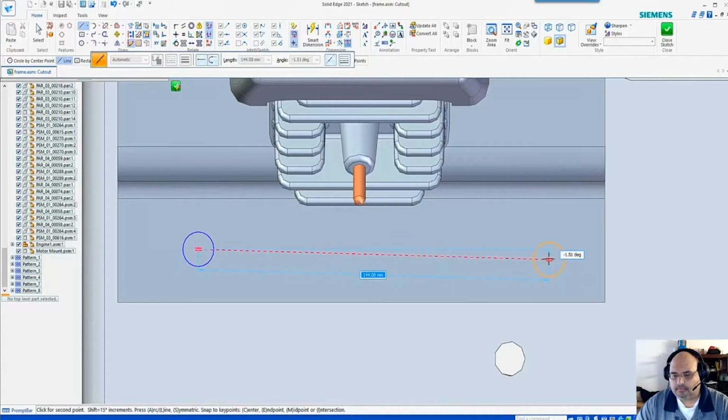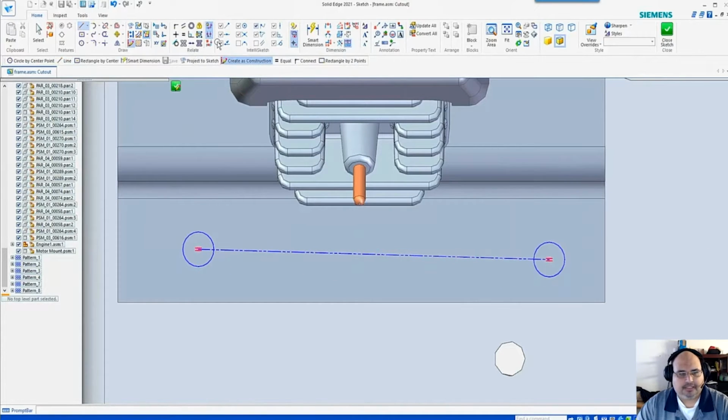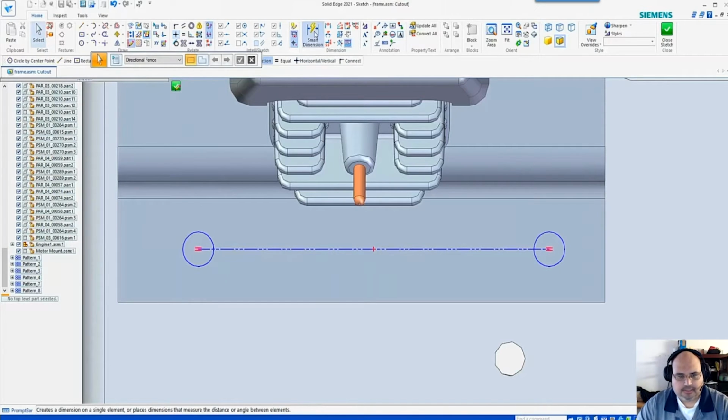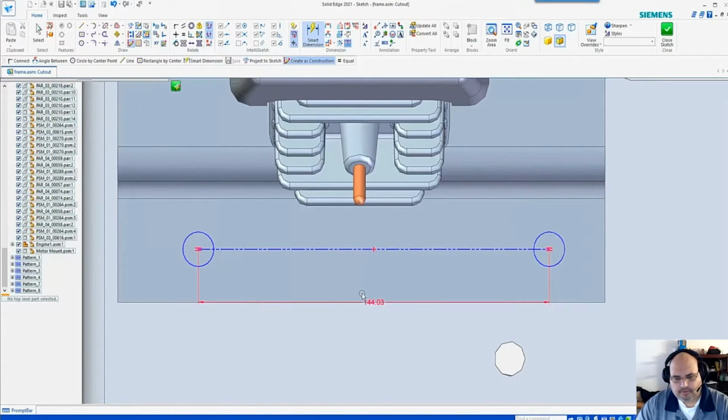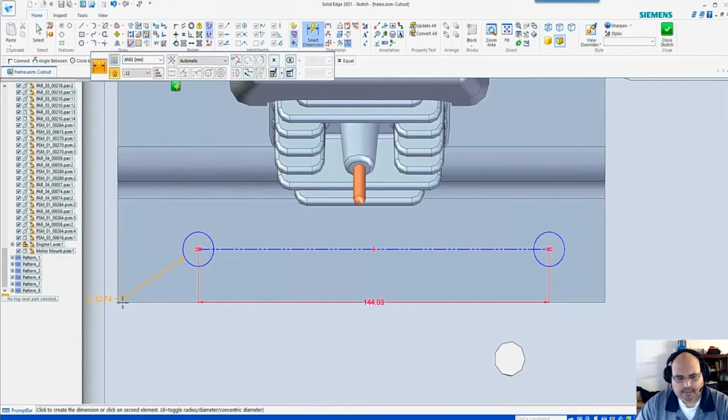Thank you. Okay, so going on from there, I connect the two, and then of course throw my horizontal vertical in there and make them aligned with each other, and then grab a center point and start dimensioning out, to give it some more definition now. So in between dimension holes, I can play around with that a little later.